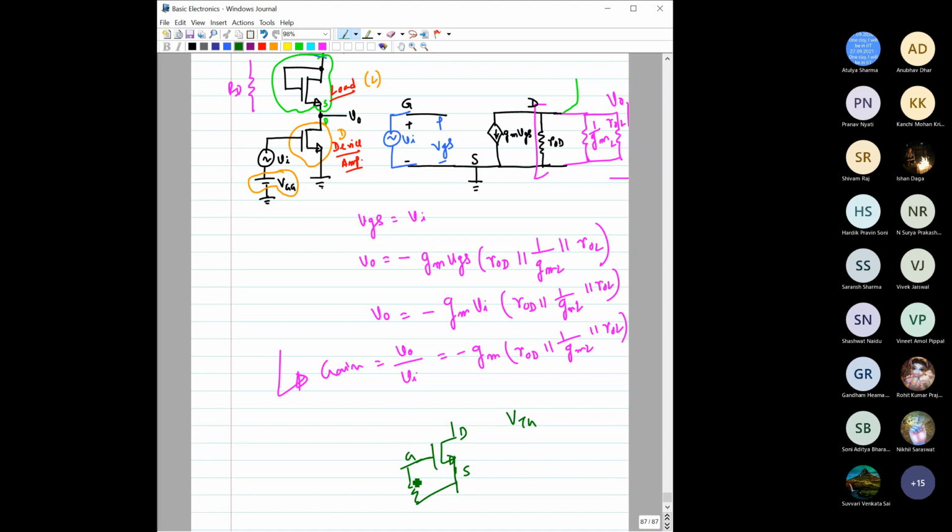Okay. And how are you connecting this gate? Means this gate is connected with what? Voltage divider? Sir, it may be connected in any way. That depends on how you're connecting this. Suppose you make it grounded, then the analysis will be one way. If you have not connected it to ground, then the analysis would be another way, right? Because the current flow through this resistance will determine the voltage drop, means what would be the VGS.